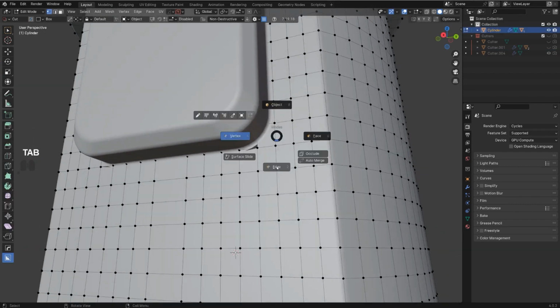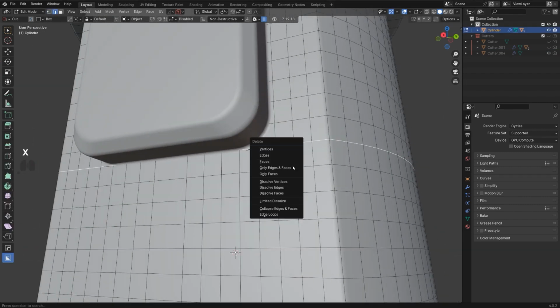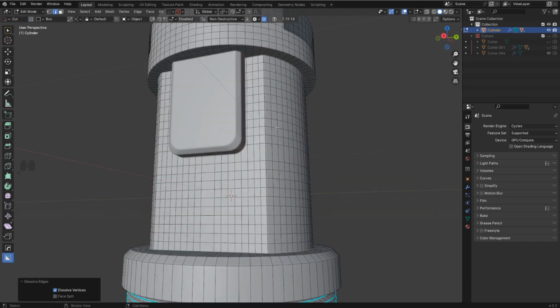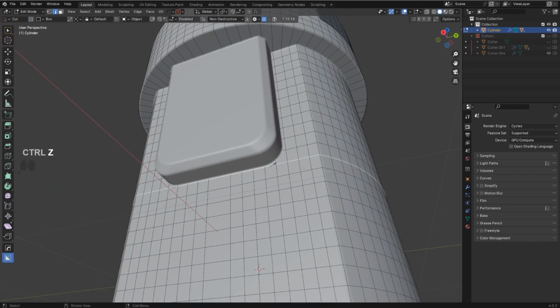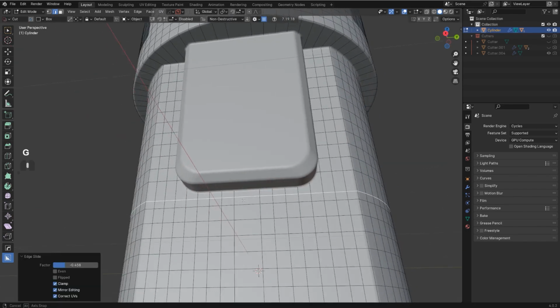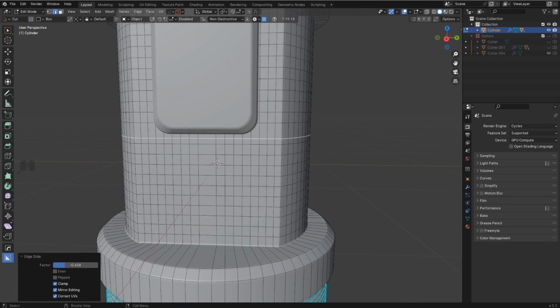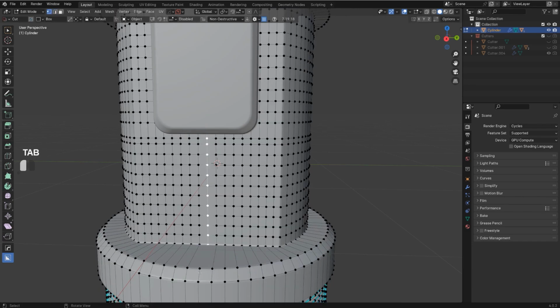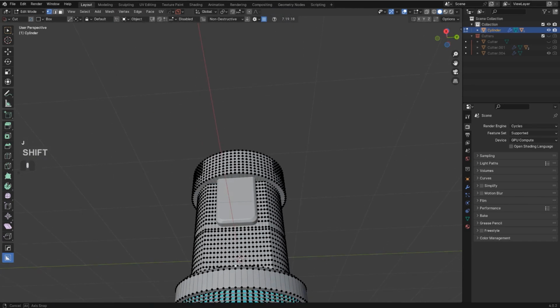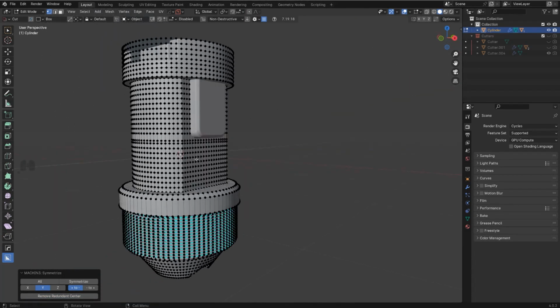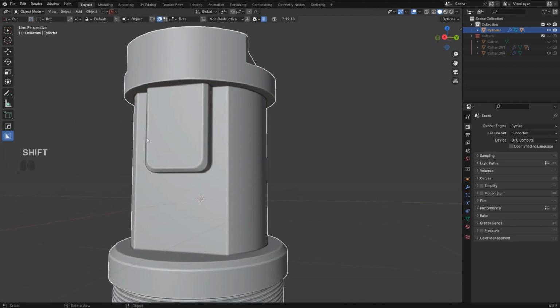Now, there's a problem in here. So what we could do is nuke this because this edge doesn't contribute to anything at the moment, so we don't need it. Either that, or you can just drop it down, okay? The one in the middle we don't need because it's a flat surface. Don't worry about it. If you really want it, you can add it and combine it, but honestly, it's not that important. You can mirror to the other side and click that, which is going to re-add the edge. Mesh Machine simply removes it by default.